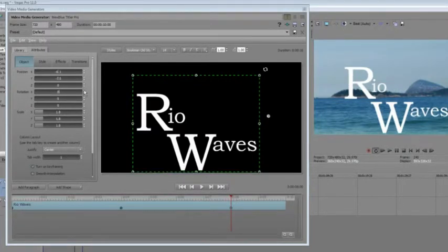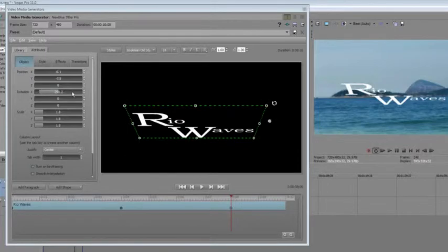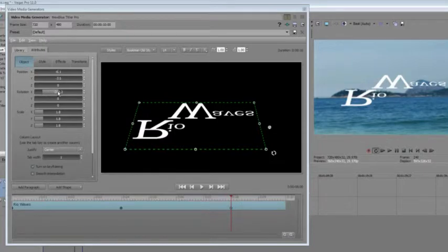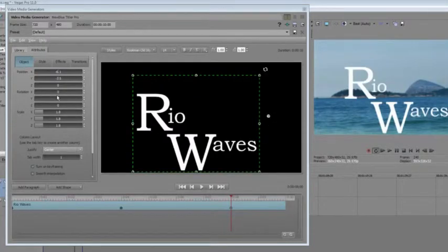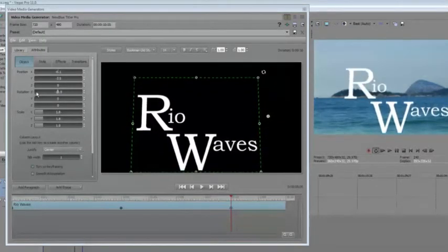Another way is the up and down arrows over here, which enable you to really tweak it in small settings. I'm going 1/10 of a point each time I click the arrow. A third way would be to just click inside at any portion of the field, and it'll set it to match the setting that you clicked on. And the fourth way, which I probably use about as much as just selecting the text, is to use this text area as a control. If you click and drag within it, it just acts as a slider.